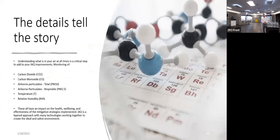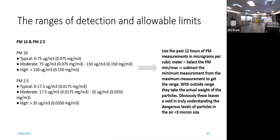Additional details on how to monitor IAQ. Details tell a story. We really need to, again, further understand not just PM 2.5, but we want to look at carbon dioxide, carbon monoxide. Again, I talked about the airborne particles, temperature, and relative humidity. Relative humidity plays an important role, as I mentioned earlier, and we want to make sure we maintain between 40 and 60%.